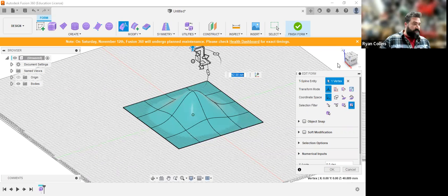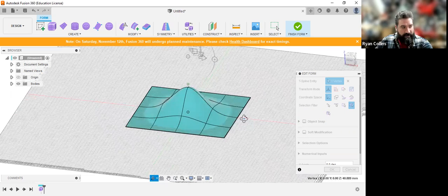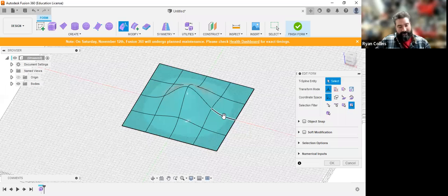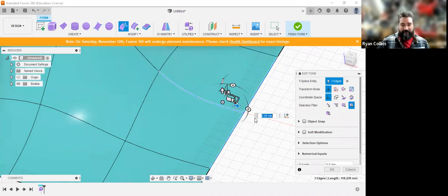And this is, let me switch to one of the other viewpoints. This is exactly like a spline. If I had a spline with multiple points, if I pull on one, the rest will follow suit. So it's not isolated from one another. Ultimately, a T-spline, the reason why they're described as that, they usually end in a T. So that edge goes down and meets the other two, and its shape makes a T. That's literally why they're called T-splines.